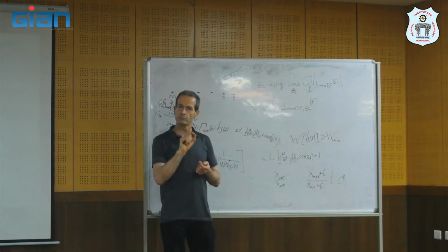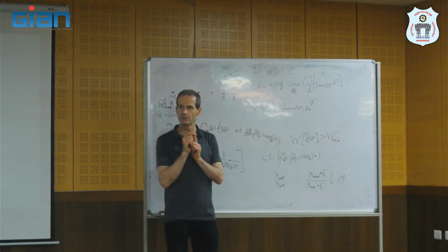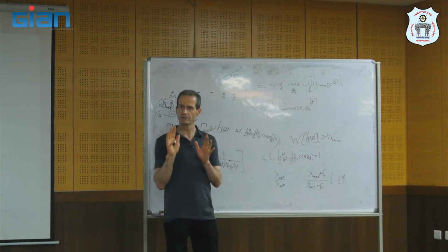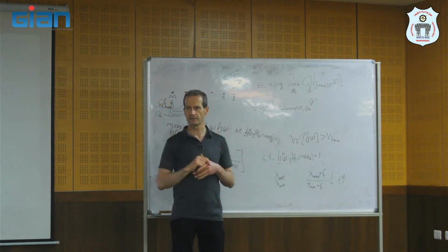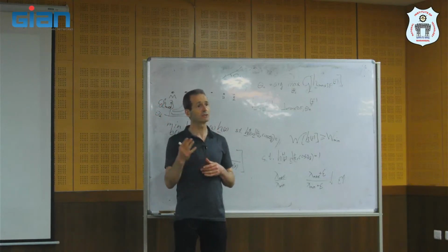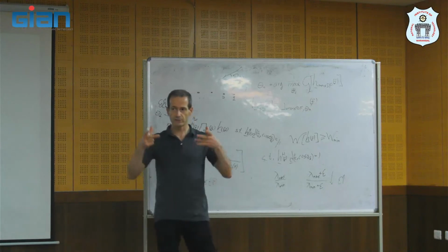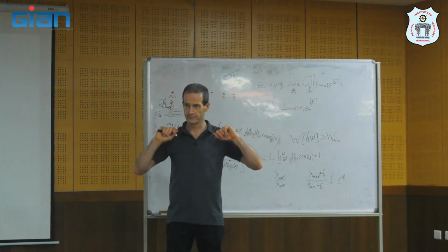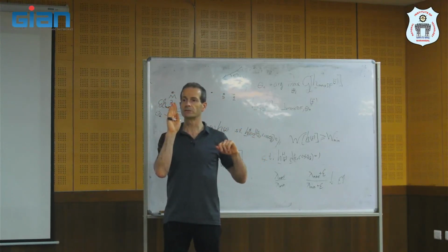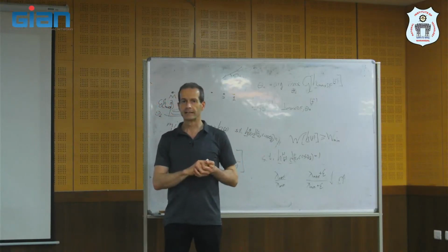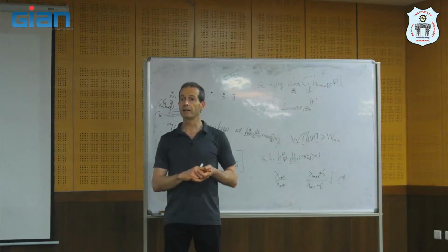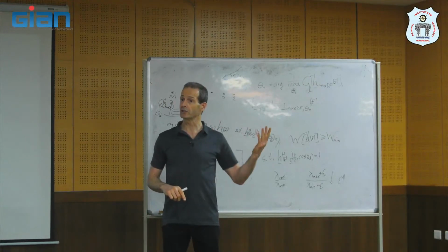So I can modify the fixed beamformer. Sometimes I do it offline in advance and I fix it. Sometimes I do it online. Suppose that I design smart glasses. I can design that the maximum response will be towards this direction, and maybe put a null on another direction.